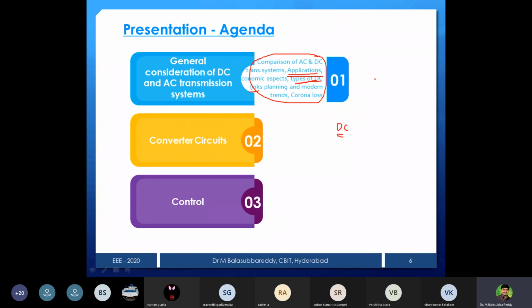In that aspect there are high voltage ratings and current ratings in those valves. So a valve is nothing but a thyristor, you can say. There is a valve rated even 125 kV, each device can withstand that, and up to 3 kiloamperes it can also withstand in the current aspect. So all these phenomena we have to explain as modern trends, how the device is going to be developed in the valve aspect, and then the converter control strategy aspect.